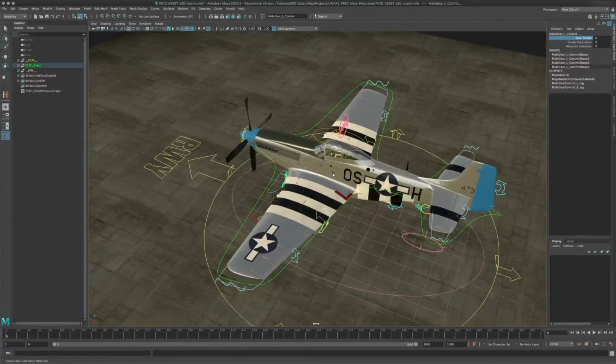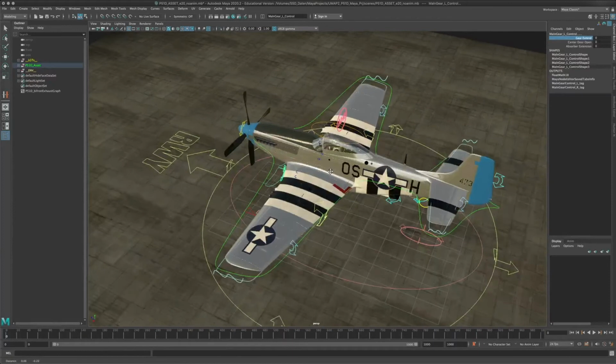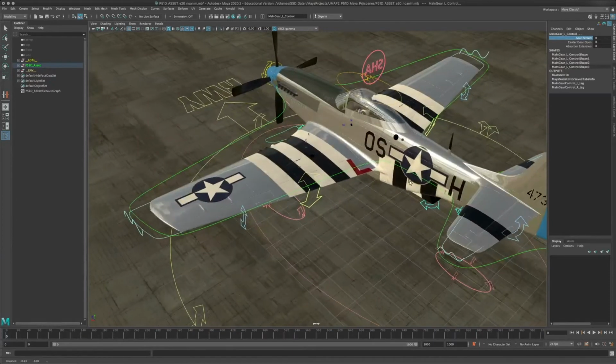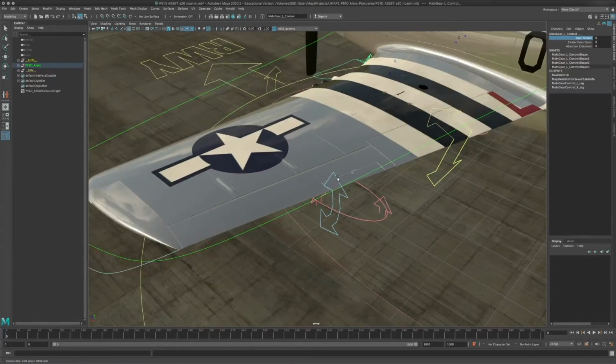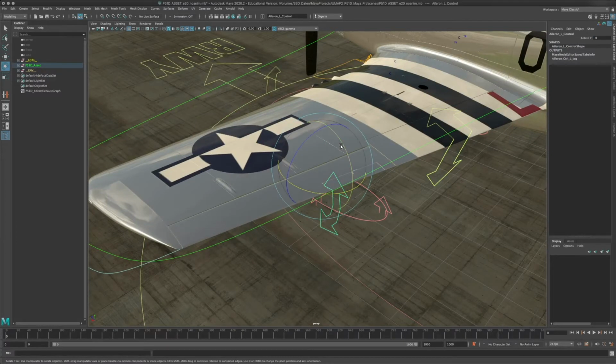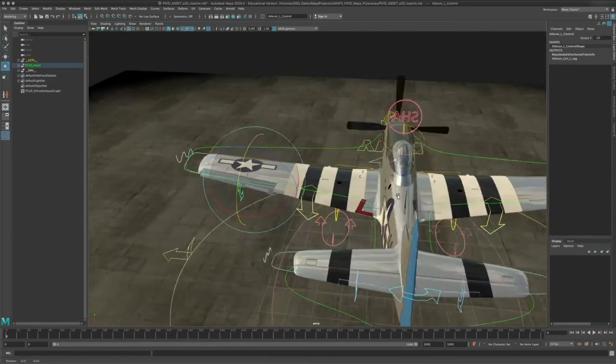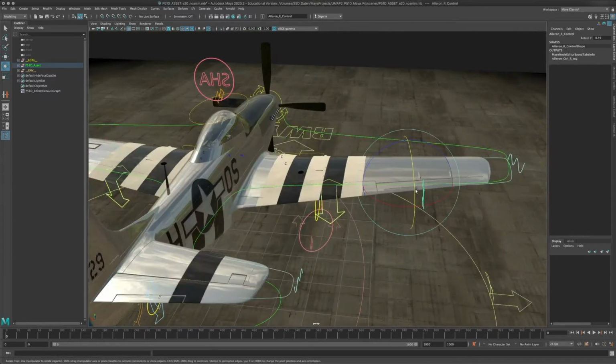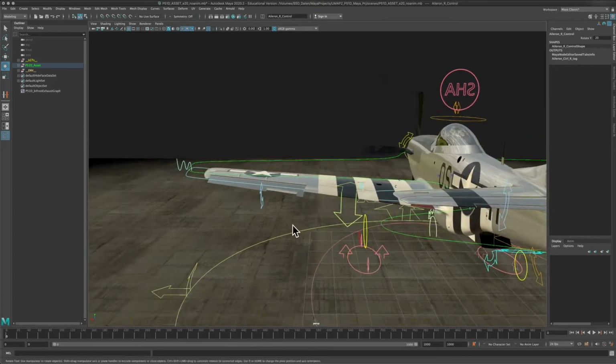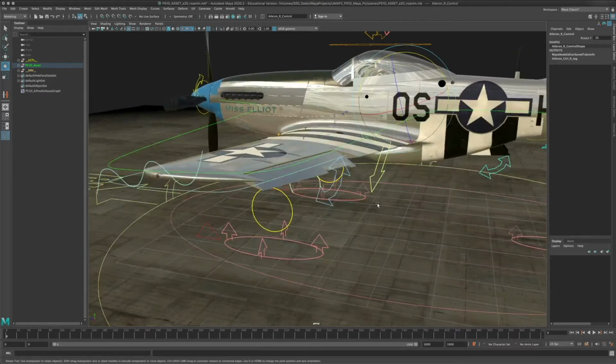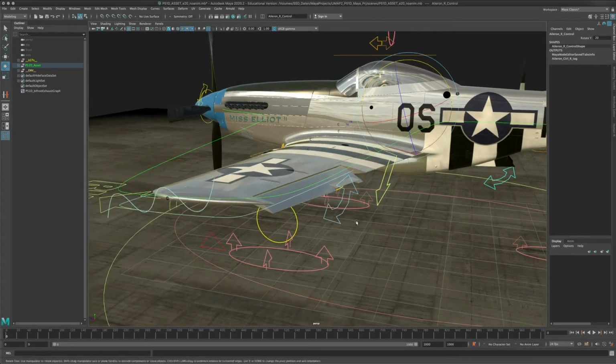Next thing are the flight controls. Let me just skim over them. That's pretty easy. These are the aileron controls. The aileron is responsible for the roll of the plane. Usually they work in a way that one aileron moves up and the other moves down, so the plane starts to roll to the left or to the right side.